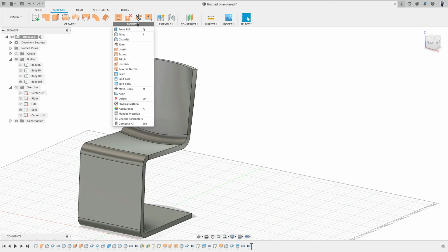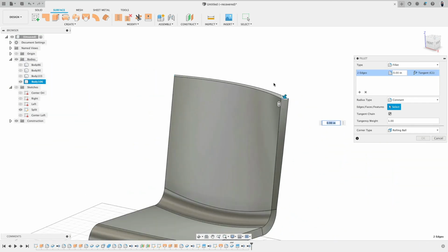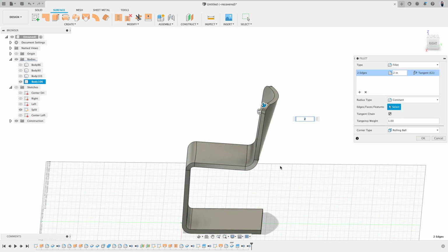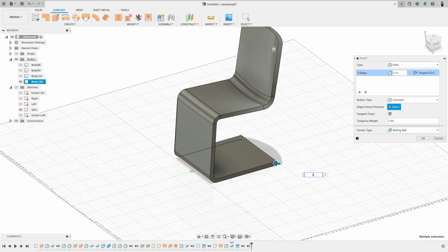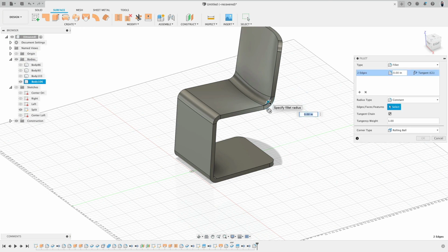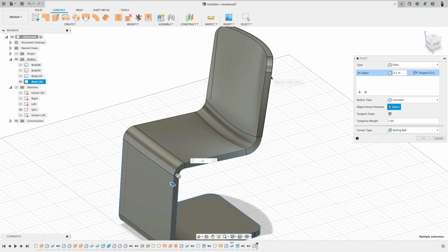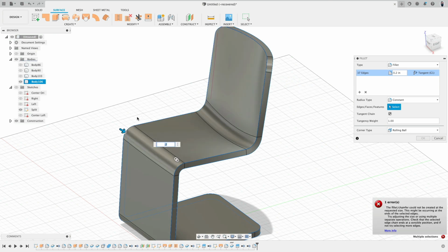Now we can go ahead now actually round this corner because we cleaned the top. Makes more sense now. Maybe 2 inches. Hold the control or Apple key. 2 inches there. Right click, repeat. Oh, interesting. I didn't really use the complete chain. I guess I might have to select all these edges there. Hold the Apple key or Control key till really all edges are selected.